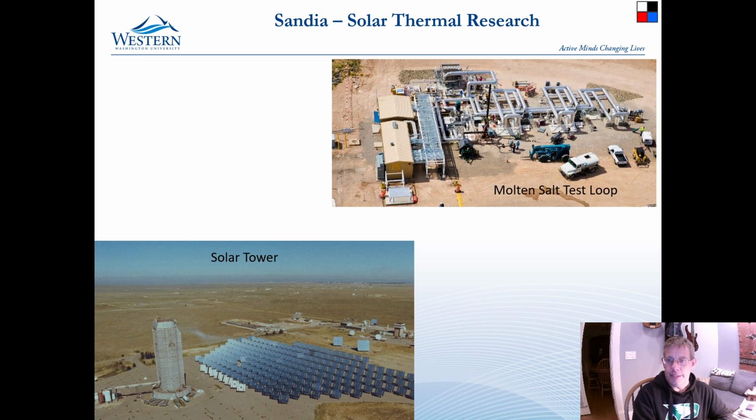And this is a huge design challenge because you have a point right here, a giant tank in the ground with 10,000 gallons in it, and you have a test fixture right here. So that's 2 fixed points, and when you heated up this piping from the temperature where you created it to 1200 Fahrenheit, it would grow by more than a foot. And so you have to do something to take up all of that expansion in the process and not tear up all the welds that are in this.